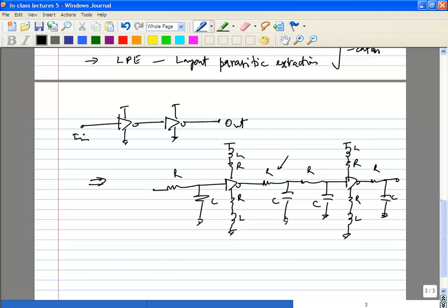Capacitance level extraction will tell you things like, let's say, the slope of your signal will get degraded if you add more capacitance, because your circuit will not be able to slew if you take an inverter. So that simple capacitance extraction will tell you. If you do RC extraction, it will tell you things like whether there are bandwidth limitations. You are trying to send a signal along a certain line. Is it really too resistive or too capacitive? There's going to be an RC bandwidth. Again, there are circuits where inductance is very critical. Simple case, you just take any amplifier, any large signal amplifier, even an inverter, let's say.